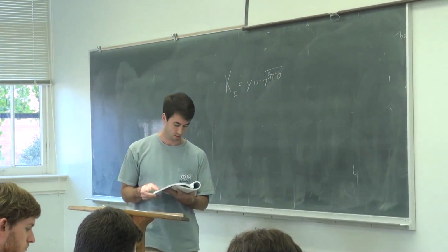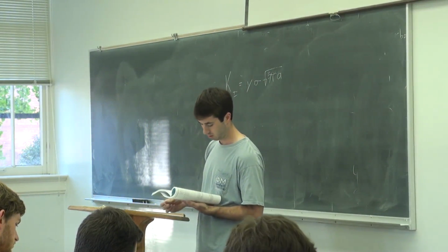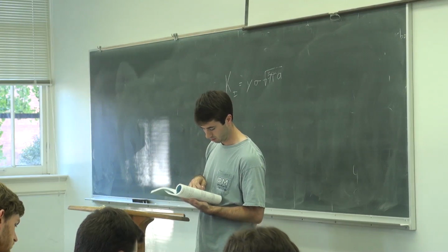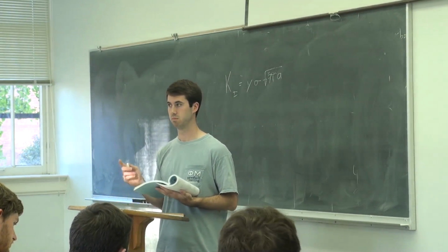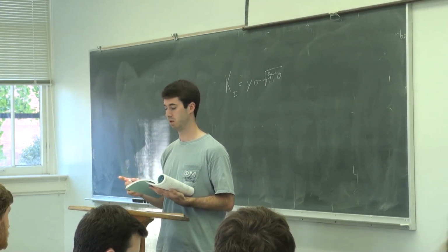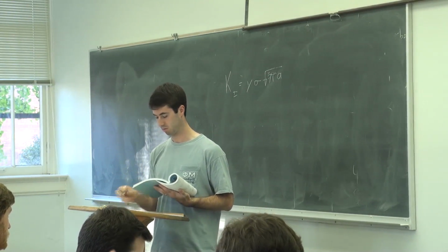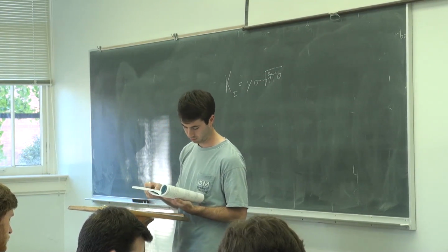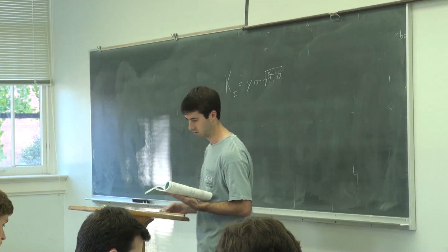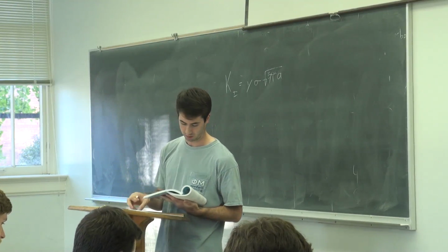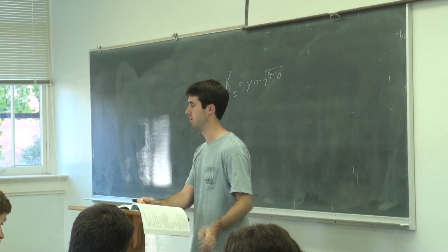The Y geometric parameter, which one do we need? 1.1. And then the stress, well, actually, we're given the stress. It says force there, but we're given stress. So we're given stress of 200, and the a would be the crack length. If you notice, this is where the FE gets you a lot. This kind of stuff you just got to be cautious of.